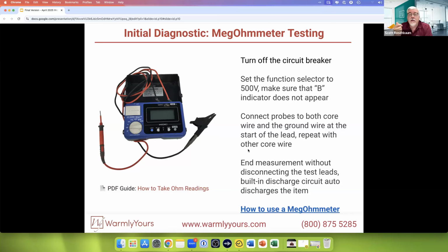And what we would do next, when we keep getting nuisance tripping on a system, is eliminate the heating mat or the heating cables by megohm metering them. If we shoot 500 volts down this wire and it doesn't trip, it tells you that wire is good. Nuisance tripping is being caused by something else, like a shared neutral on your power supply. It could be a wiring issue where you're taking a tap off of an individual box somewhere else and sharing it into another box. There's a lot of things that we've seen,